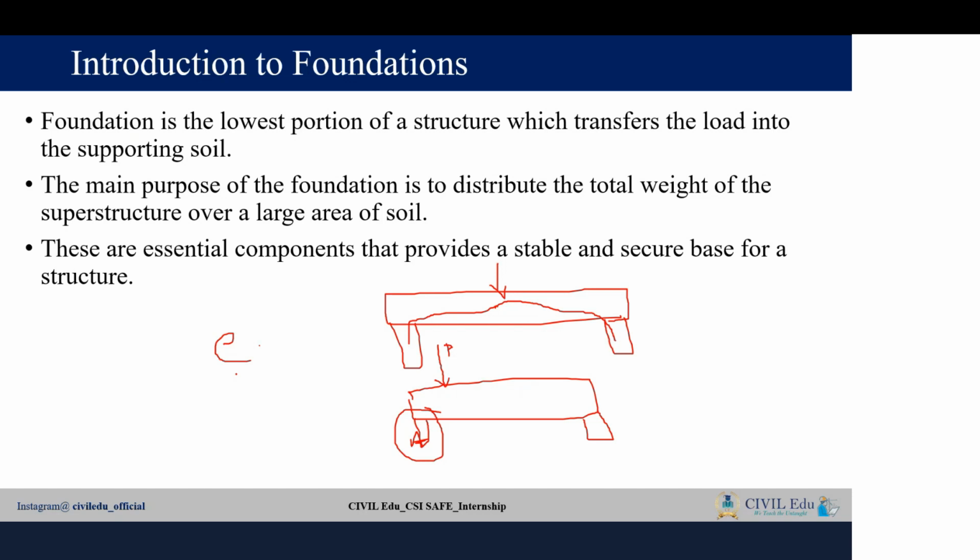I'll be talking about this particular point in the manual design and Excel, I mean, in the software design calculation. There I can show you in a better visualized way. But remember that the loads need not act exactly at the center of the structural members. So some structural members will face an eccentric loading.